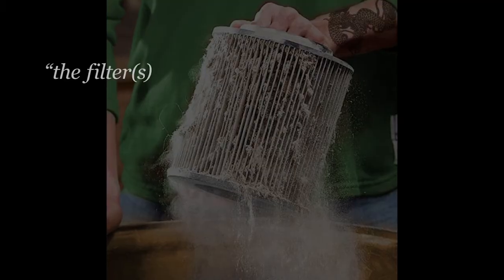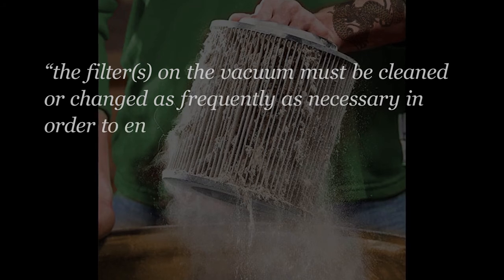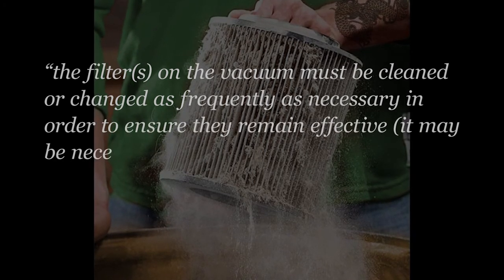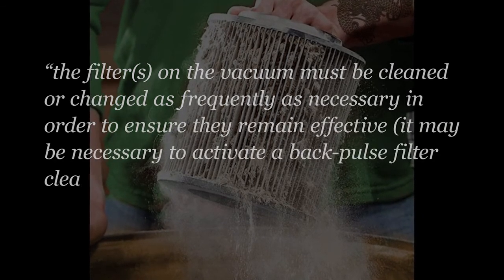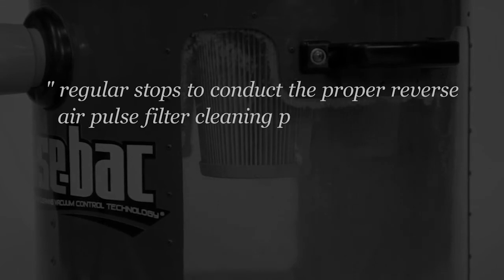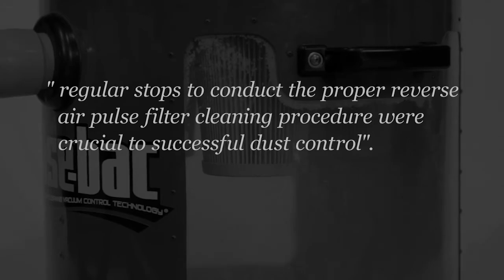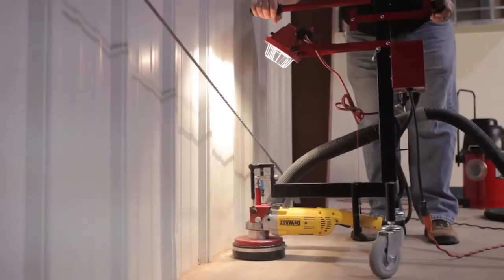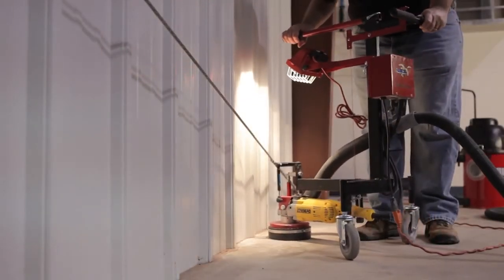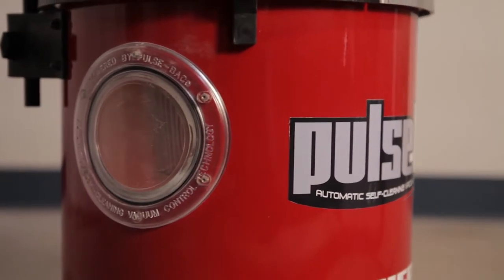Quote, "The filters on a vacuum must be cleaned or changed as frequently as necessary in order to ensure they remain effective. It may be necessary to activate a back pulse filter cleaning mechanism several times during the course of a shift. And regular stops to conduct the proper reverse air pulse filter cleaning procedure were crucial to successful dust control." Then in a different section we find the statement, "To assist employees in determining when it is time to run a filter cleaning cycle, vacuums equipped with a gauge indicating filter pressure or equivalent device, e.g. timer to periodically pulse the filter, may be useful."